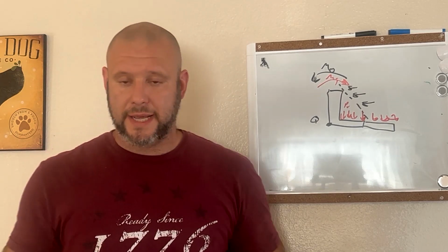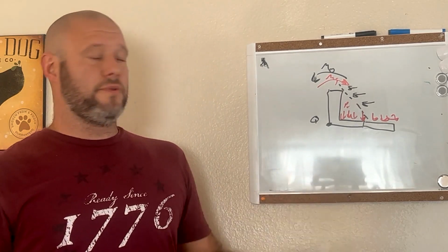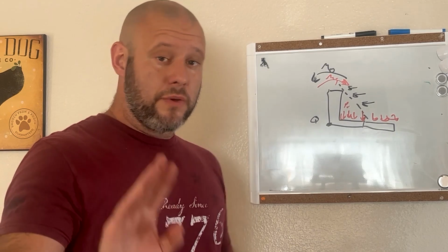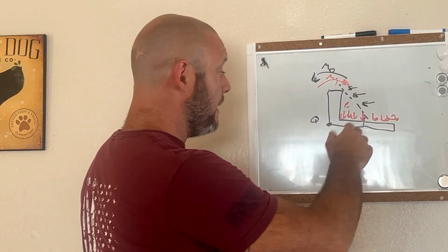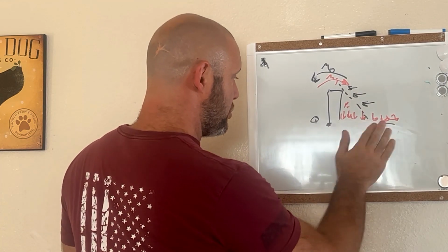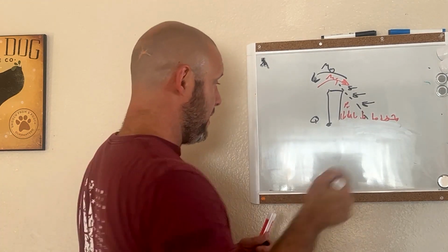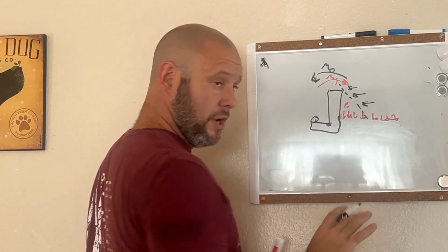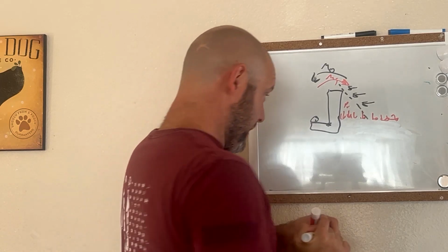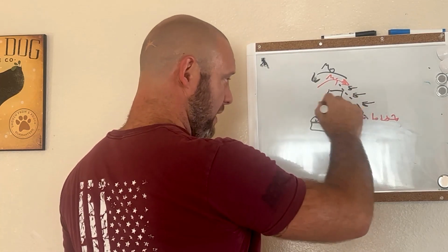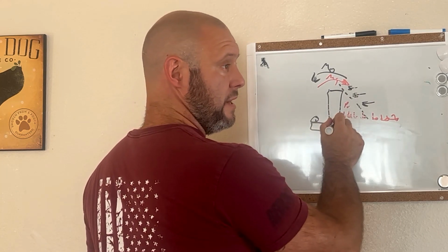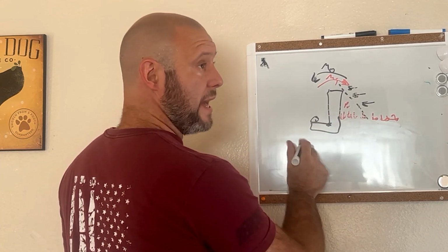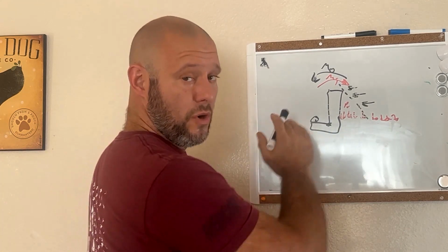So if I'm designing a hillside project and I have absolutely no idea what's going on here, you have to be careful about things like injection grouting. If this is short, or especially if this retaining wall was designed backwards, which we've determined shouldn't be, but maybe it is, and you inject grout here, which increases the lateral pressure on this retaining wall, you could create a sliding moment and push this whole thing out, right?